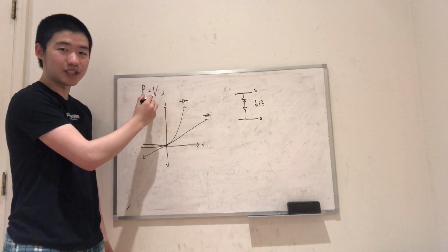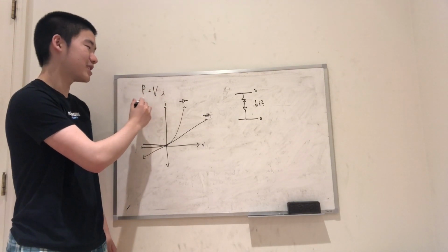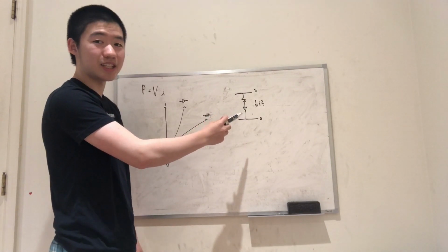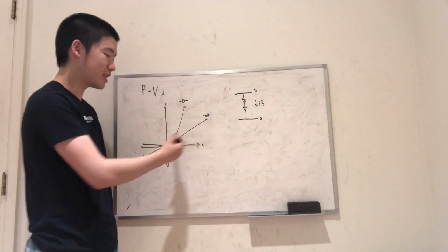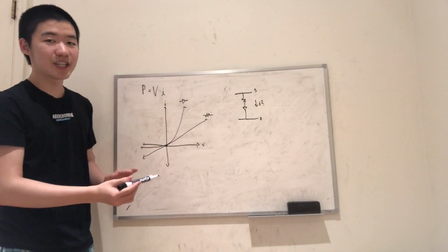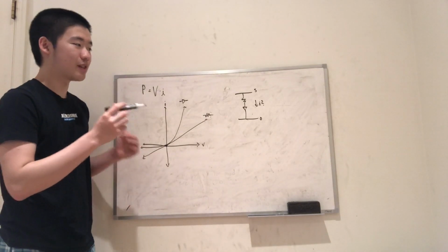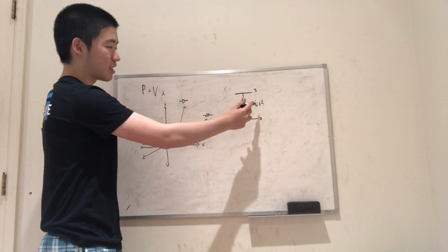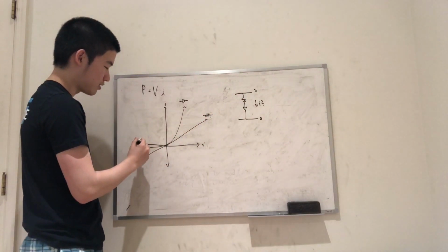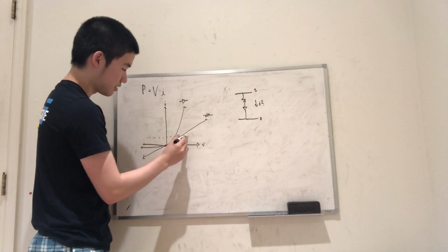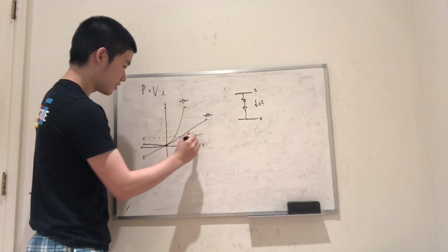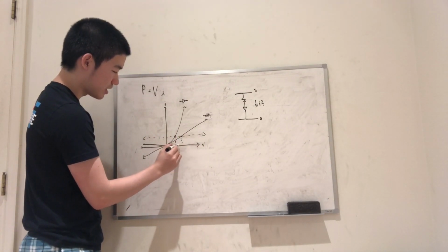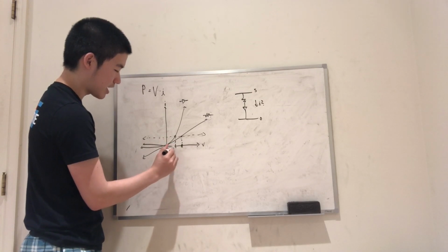So if we know voltage is always 5, then this problem is essentially saying how do we minimize current? And in this case, we actually can't minimize current because we are already given a fixed IV curve, so then we will have a fixed I value. Since we know that current must be constant, if we draw a dotted line across here, and then find these 2 points, we should find that these voltage values here add up to 5.